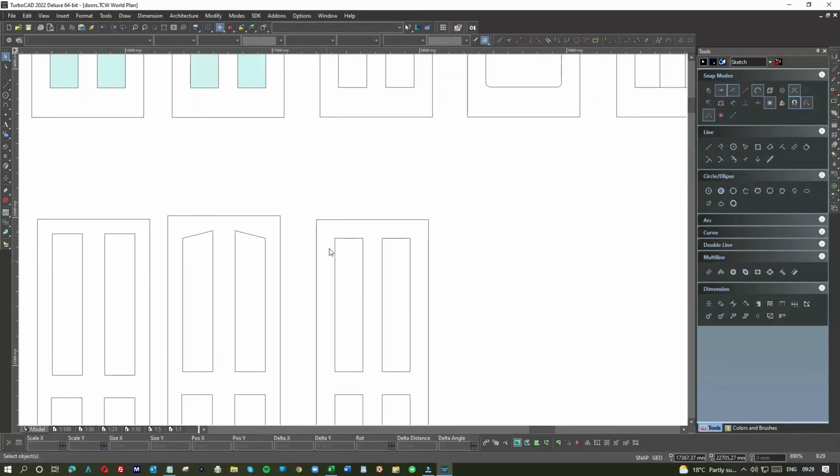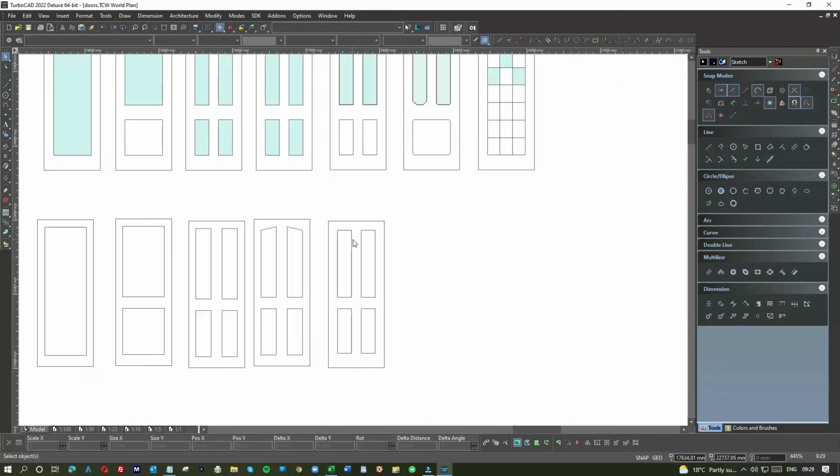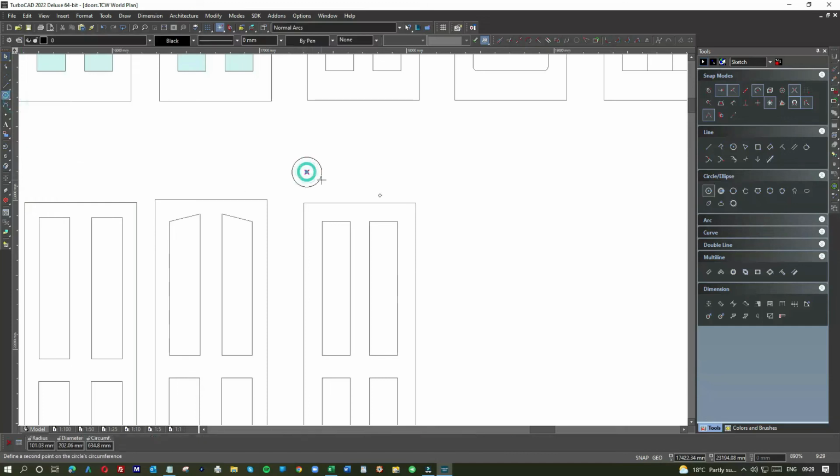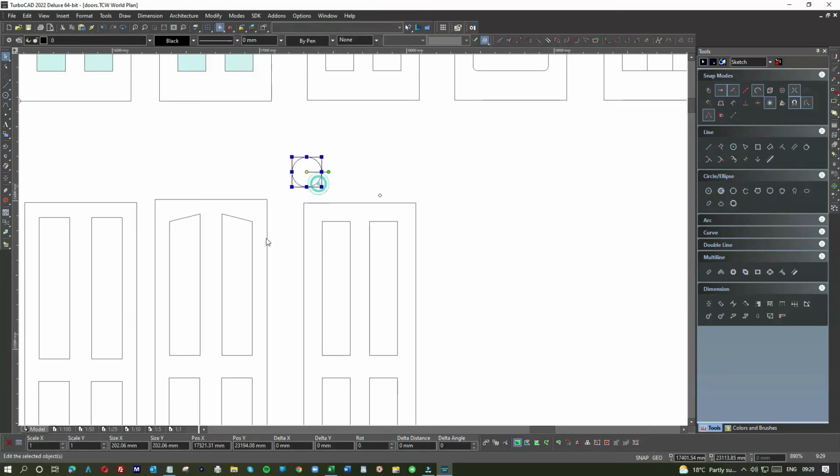Right, we were looking at doing a little semicircle on the top here. So let me try that. Let me just bring up a semicircle. Let me check the width of this, 191. So if I do a 191, tab 191, semicircle, I'd be doing fine, wouldn't I?